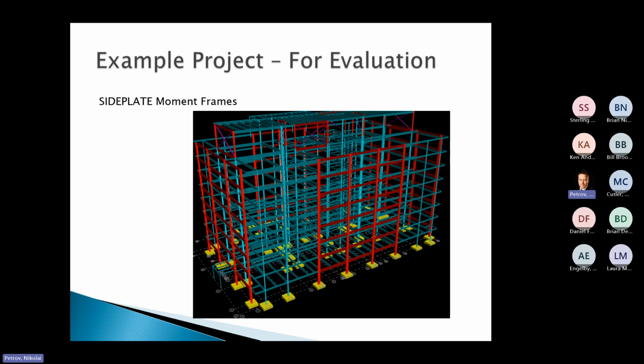We'll even tell you how much it would cost if we were doing this building. So they decided, just for the purpose of marketing this to design build contractors and other people, they'd go down this road with us. So here's the model that I made. And as you can see, I've taken the moment frames and I've pulled them to the perimeter of the building, leaving nothing in the core of the building except gravity.